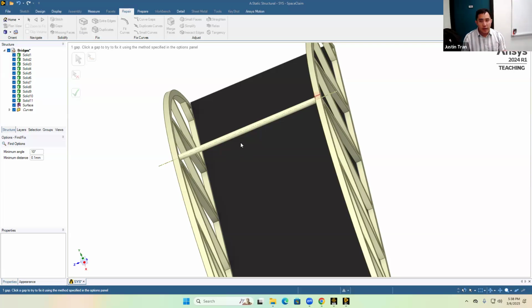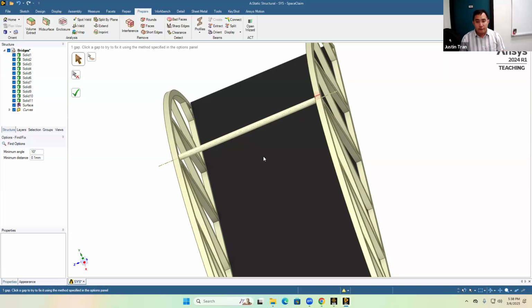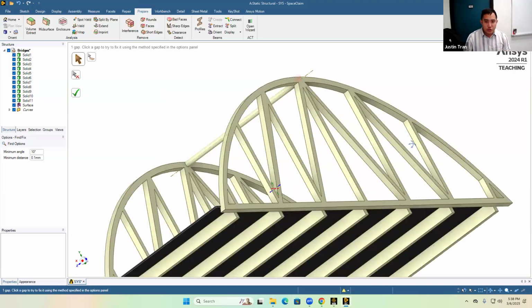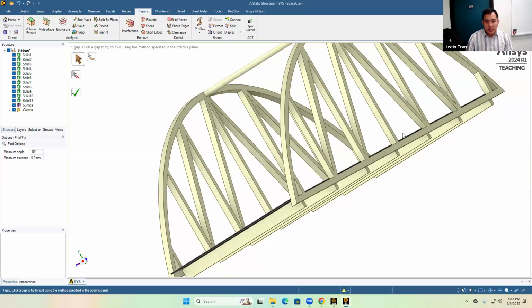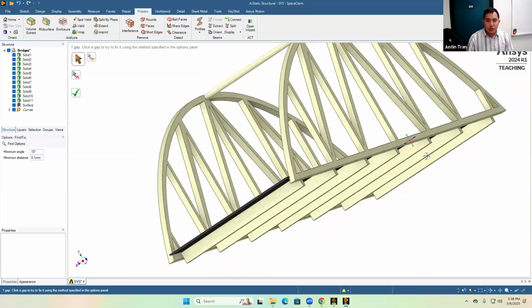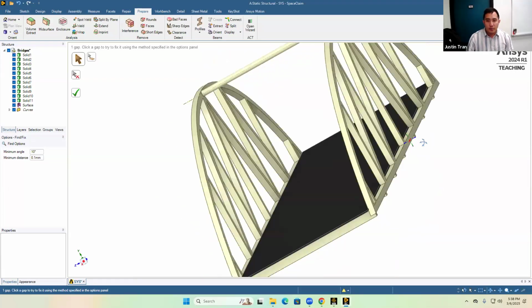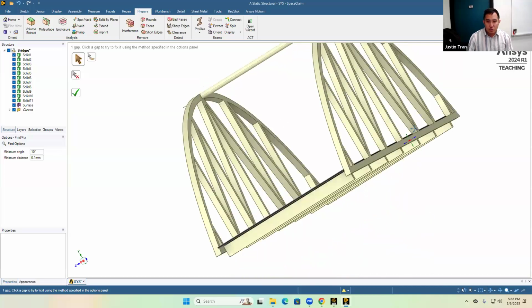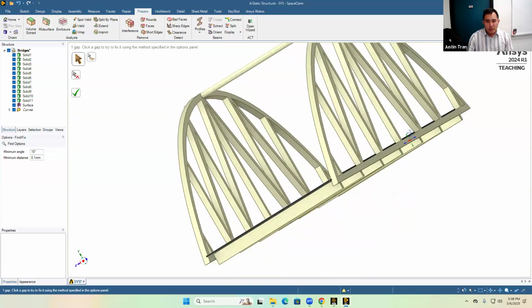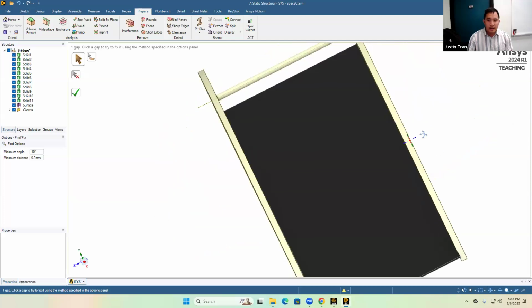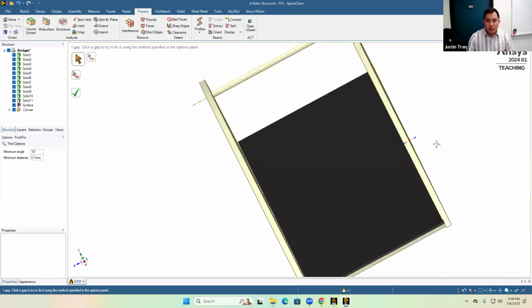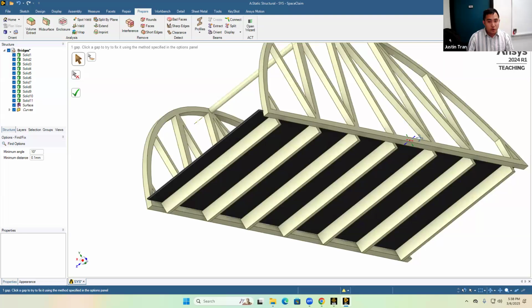Okay, all right. So now that our model here is relatively clean, let's go ahead and start working on converting it. If you look at this geometry, you can see there are a lot of aspects of the geometry that we can convert to shells and beams. First, the most obvious one is this road. This road is this very thin, black sheet here, so this is one that we can convert to a shell.